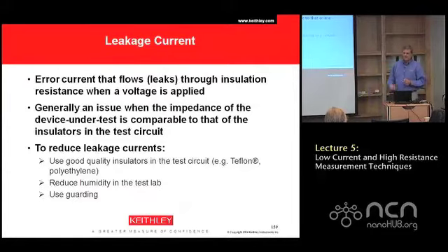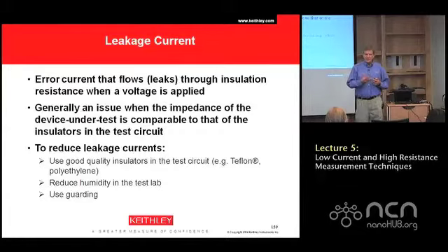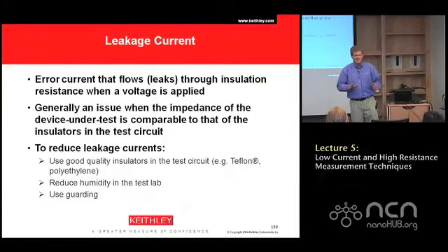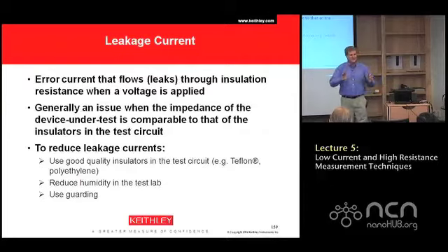Okay. Now, most modern labs, certainly here at Purdue, they have air conditioning, controlled environment, but the truth is the facilities probably doesn't always have great control in the lab. A lot of times I'll see a facility will shut the air conditioning off at night and the lab will go to 80 degrees Fahrenheit and 60, 70% humidity, right? And that humidity sort of coats everything. It coats the circuit boards, it coats everything. And then, of course, the next morning at 7 o'clock in the morning, they turn the air back on. The whole room comes down.